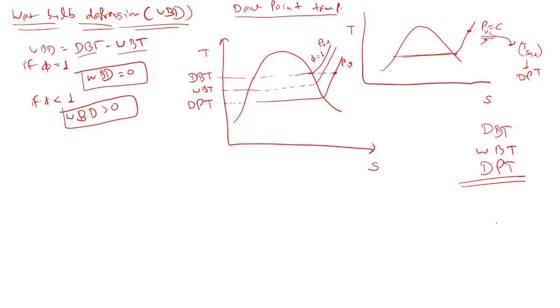Yes. So here you have also seen that vapor pressure increased at the wet bulb temperature. Is it so? Have you been able to see that? Because here it is the PV of WBT. Vapor pressure has increased when we are looking for the wet bulb temperature. What does it mean? It means air has absorbed moisture, the more molecules of water vapor, so its pressure got increased. What would be that pressure? This would be that pressure. Is it okay?